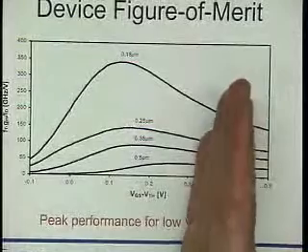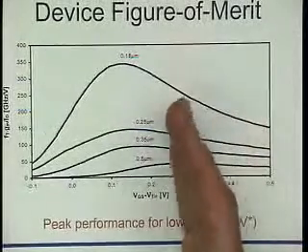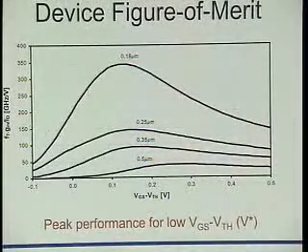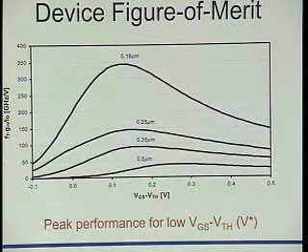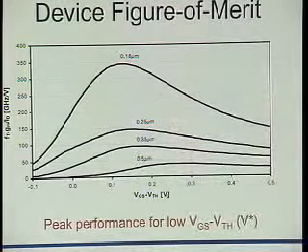Right, if we make VGS minus VTH, which is approximately, but only very approximately, equal to V star, very small, then we are in weak inversion. We have good current efficiency, but slow speed, and then over here we get to very high speed.